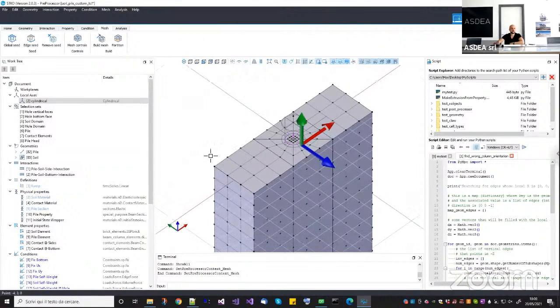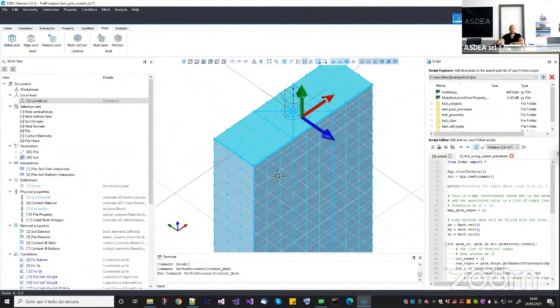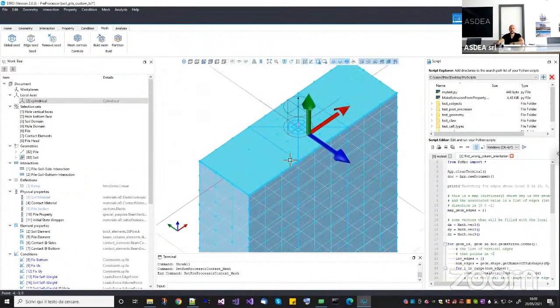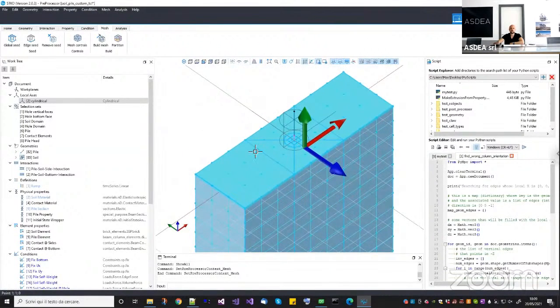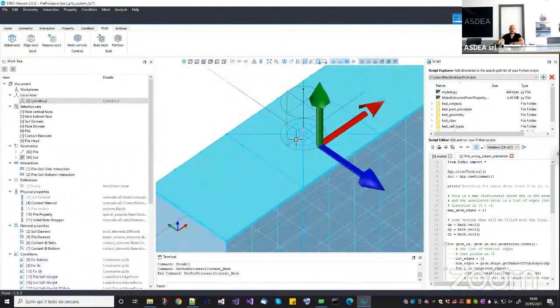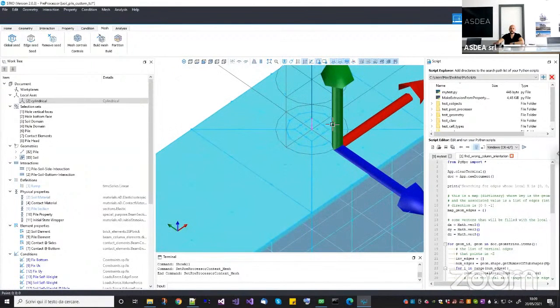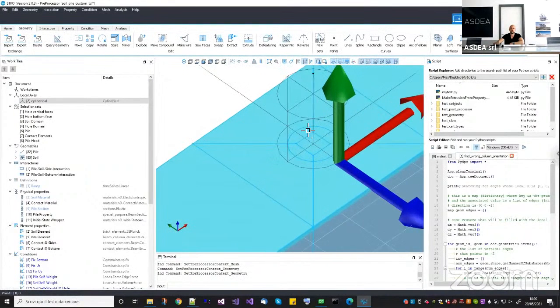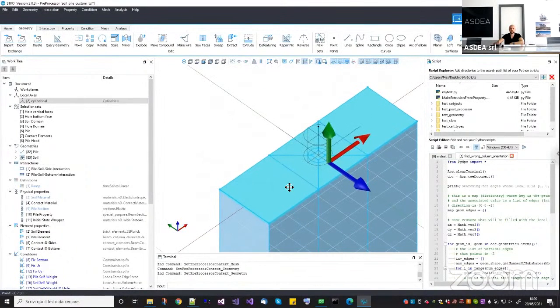And to do so, you have to make sure that every solid inside this composite solid domain is made of 6 faces. That's why when I created this geometry here, I needed to create a hole here with a cylindrical section. Let me go to geometry so you can see it better. So this one is a cylindrical section, a circular section. And to make sure that each one of these faces can be meshed with a structured mesh, you need to divide it. Okay, so the construction of the solid was quite simple.